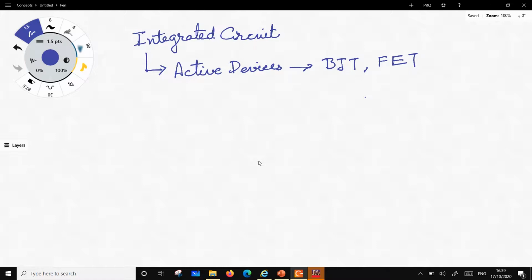Then we have a metal junction, right? So it can also be used as just a metal junction with semiconductor, so that will be called a MESFET. Right? And then there are other variations of it, like for example, they call high electron mobility transistor or HEMT. Right? So this is a specific type of field effect transistor. So let's put here. So we have MOSFETs. Okay, most of the silicon is dealing with MOSFETs. Then we have got what you call JFETs, or junction field effect transistors, right? You can call it that way also.